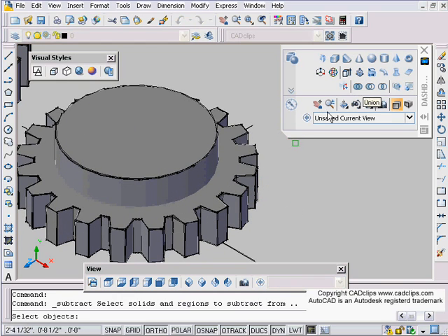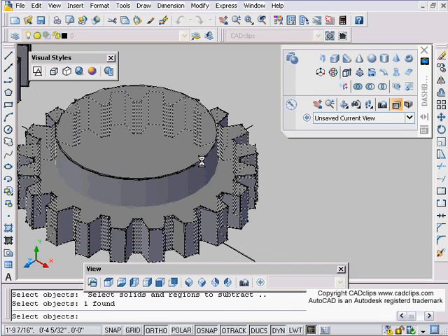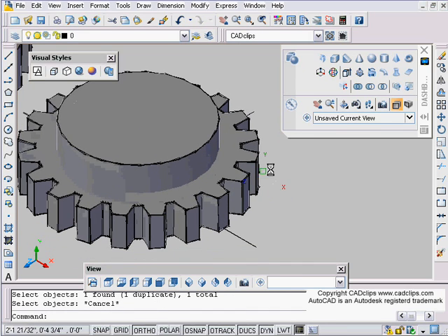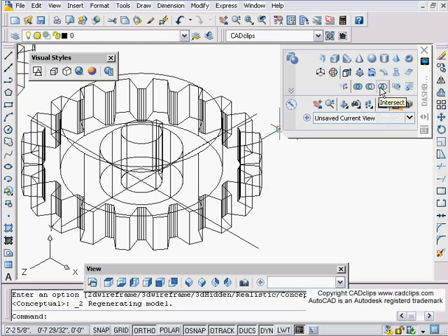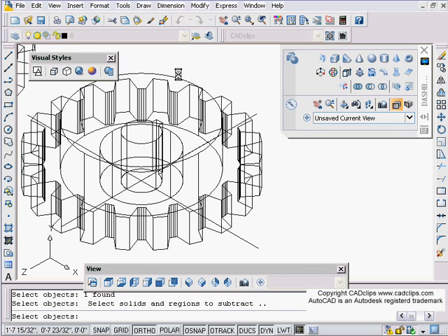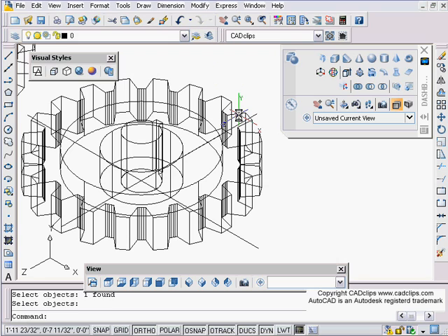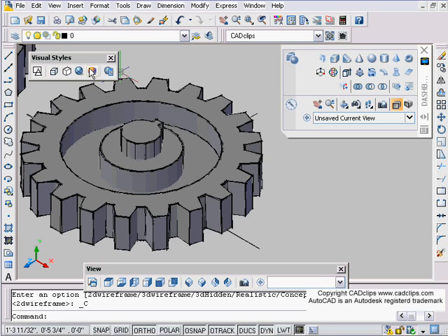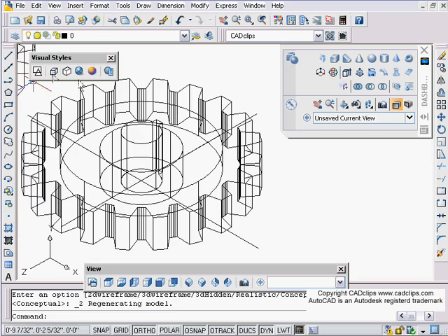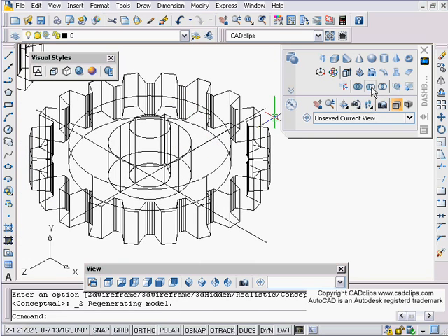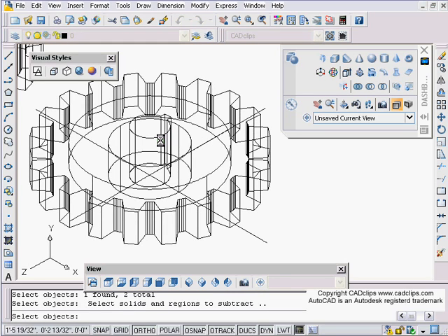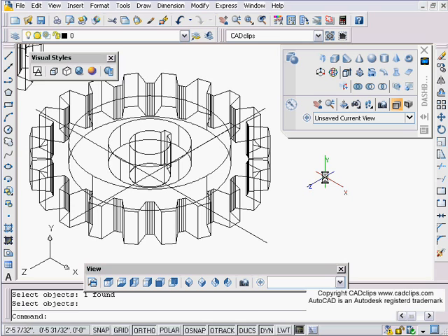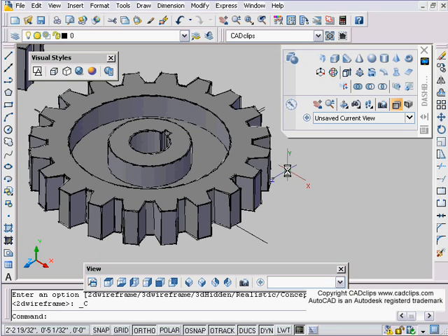So now what I'm going to do is I'm going to use my subtract from here, enter, okay, I might have to use my object cycling here. Let's switch to wireframe and see. So let's go subtract from here, enter this, enter. Okay, so that removed that. Okay. Now I'm going to go back to here. It seems to be easier to select. Now I'm going to say subtract from the big one and this one, enter this, enter. Okay, that's going to create the hole.